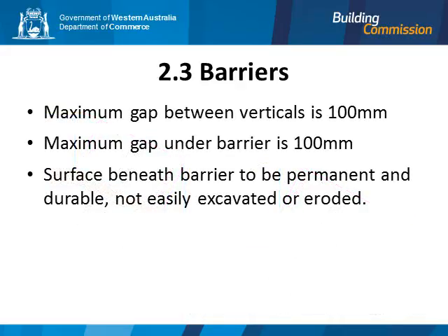The same as the 1993 edition, the maximum gap between vertical members is 100 mm. The maximum gap under a fence or gate is 100 mm. The surface under a fence or gate should be durable and not easily excavated.